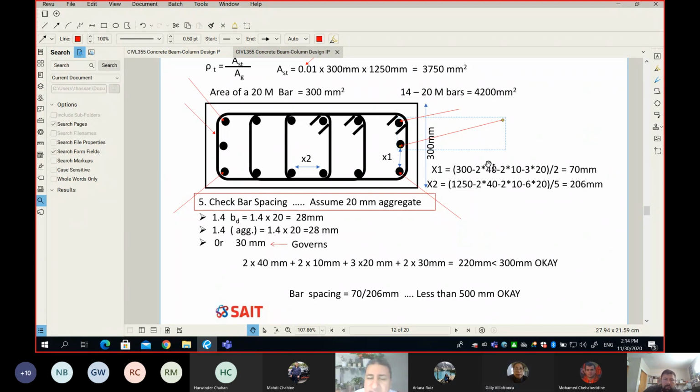This bar in the middle along the 300. Is it okay? It's okay because without it, it's more than 150. Exactly, Gord. What you have to do is estimate the x1, and I think we already found x1. So as long as x1 is less than 150, it means the tie is so short that it can confine and restrain this bar from going outside.